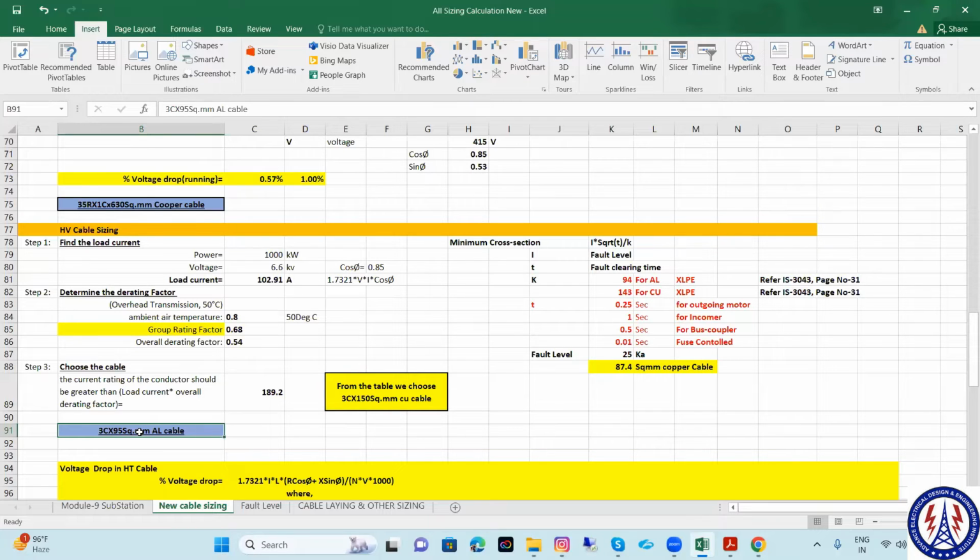And how about the fault clearing time? Is it as per the standard? It's not a standard. The standard will not tell you anything. The thing is, my relay should trip within this time. How do we decide that it is within 1 second? How is the criterion verified? This is verified by the relay coordination only.